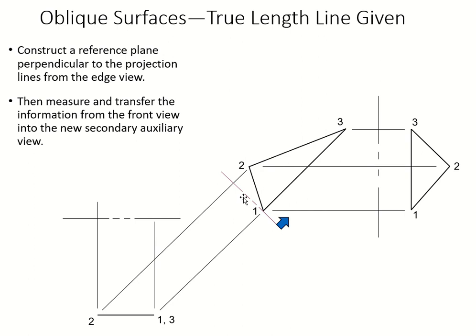We're going to put the fold line close to there. The fold line can go anywhere in between the two views, so don't worry about moving from here to there. You can do that. So now we're going to move it closer to the middle view. And now let's start projecting 2 and then 1, 3 to our third fold line.